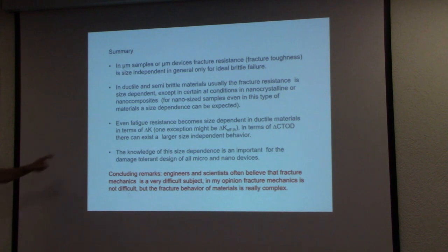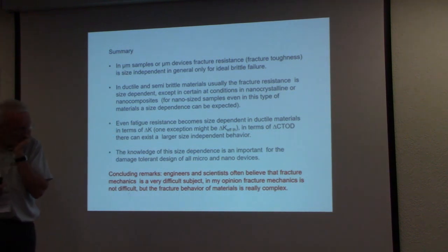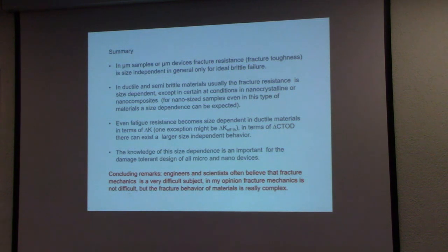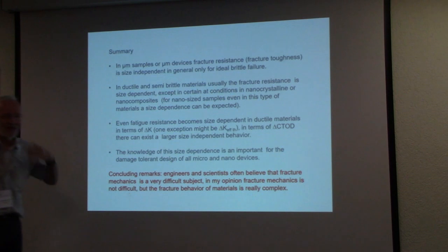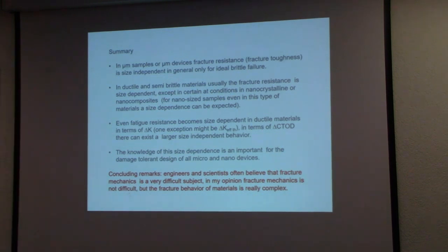In fatigue, the behavior will be quite similar to the case of the toughness, except for the threshold value, because at the threshold the cyclic crack tip deformation is in the order of the lattice spacing, and since the cyclic plastic deformation is in the order of the lattice spacing, the fracture process zone is small compared to all the other dimensions, and therefore we can use fracture mechanics.